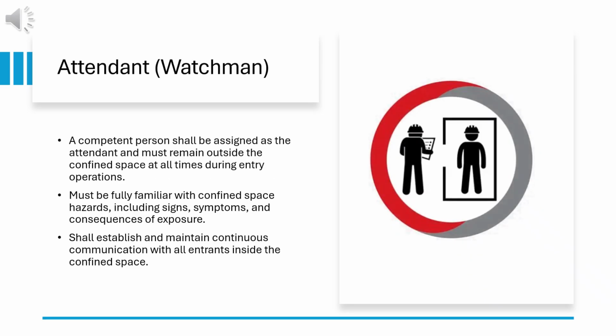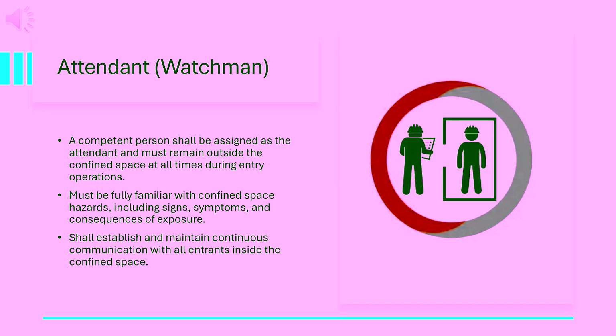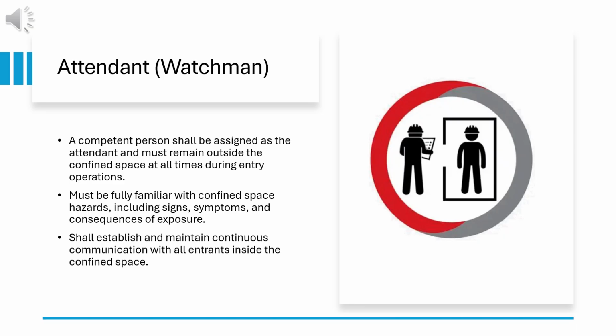Attendant role. A trained and competent attendant must remain outside the confined space at all times. The attendant must understand all hazards and recognize symptoms of exposure. Continuous communication with the entrants is required. The attendant plays a critical role in ensuring safe operations.